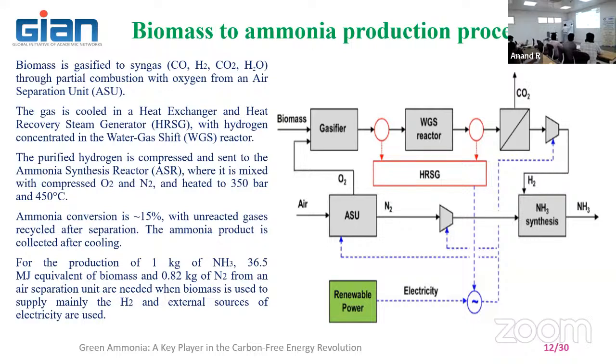Ultimate analysis talks about CHON, presence of carbon, hydrogen, oxygen, nitrogen, sulfur. For biomass, sulfur is going to be approximately 0%. That's the reason why in biodiesel production, we are using non-edible oil to produce biodiesel, which can have the equivalent quality of the diesel, which can be used in the diesel engine directly without any modification. Approximate analysis, we are finding out the fixed carbon, moisture, ash, then volatile matter.